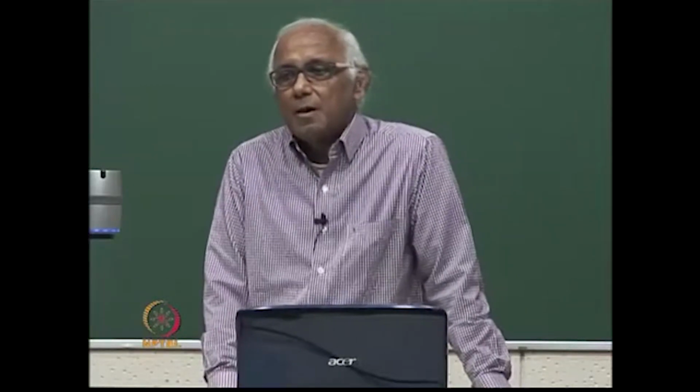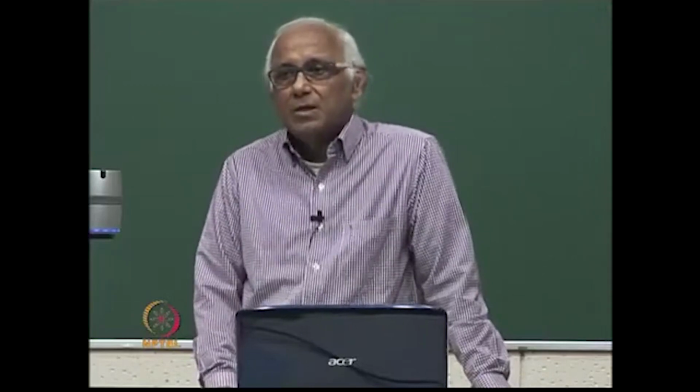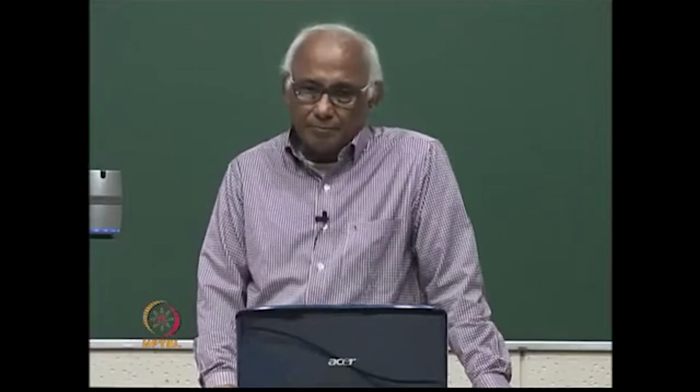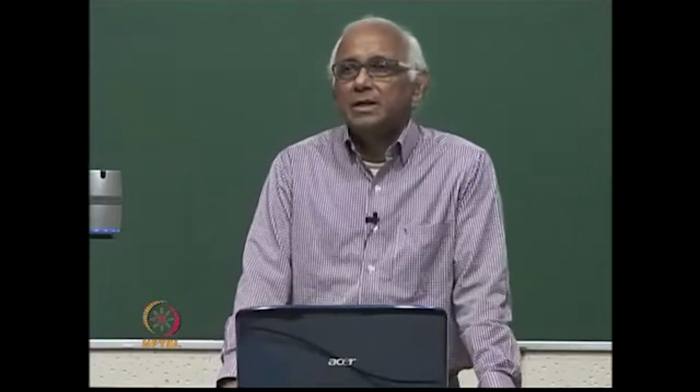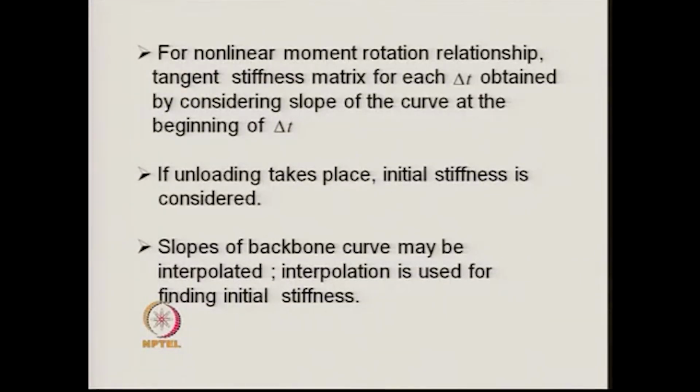These two stiffness matrices are added together, averaged, and with the help of that average stiffness matrix we find out the final incremental displacement or response over the time of delta t whenever the system is unloaded. However, whenever the system is not unloaded but is monotonically increasing over the curvilinear force displacement relationship, then we go on calculating the tangent stiffness at every interval of time t.